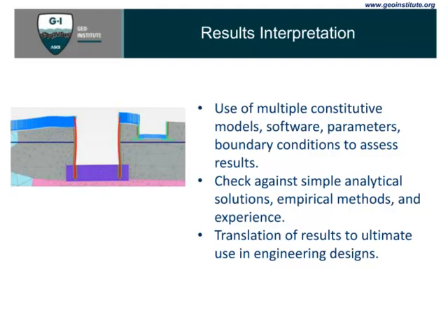And of course, for most situations that aren't trivial, you would almost always check your results against an analytical solution or empirical models as appropriate. If someone is running a numerical model of a deep excavation, almost everyone is going to check the deformations against something like Clough and O'Rourke.